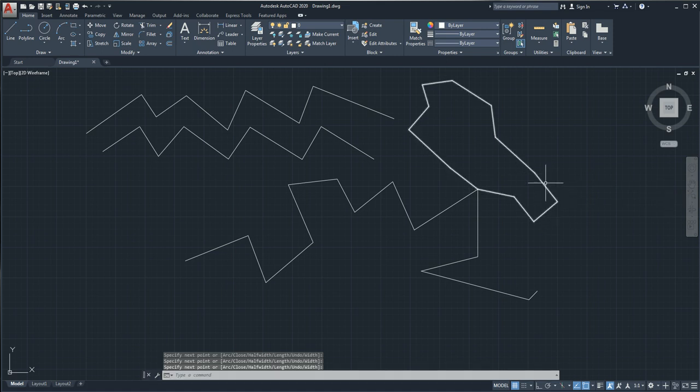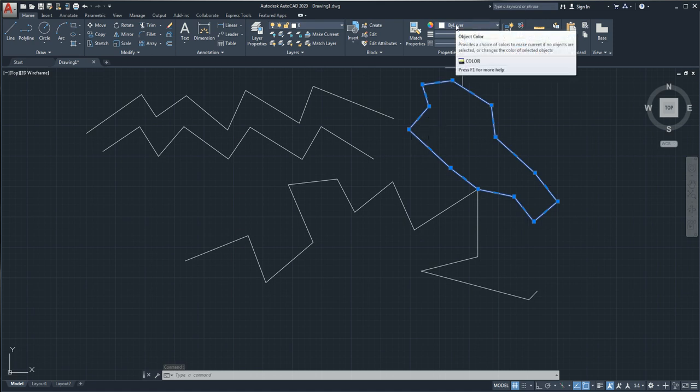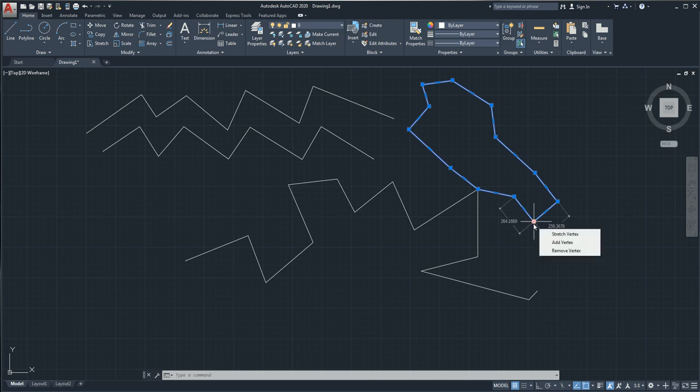So they don't have to pick separate lines and do hatching, center lines or dash lines, or change the color of those lines. Once they are using polyline, they can just pick any one of them and change the characteristic they want, either the type of line or the color of this line. This gives you the privilege to do something like one continuous line if you have an irregular boundary. So this is the difference between line and polyline.